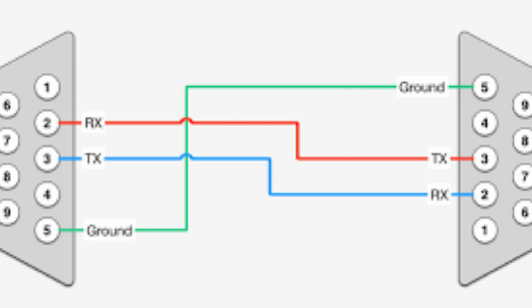There are many commonly used RS-232 modules that can be integrated into electronic devices, computers, and other systems. Here are a few examples of commonly used RS-232 modules and their compatibility. UART, Universal Asynchronous Receiver/Transmitter. The UART is a common RS-232 module that is used to convert parallel data to serial data and vice versa. Many microcontrollers have a built-in UART, making it a common choice for embedded systems.